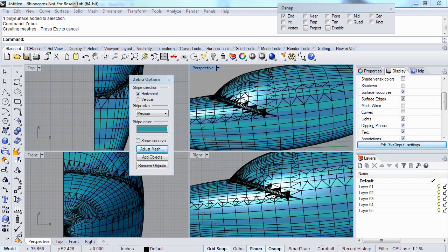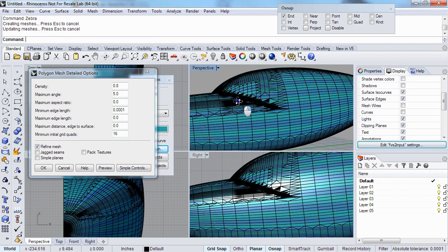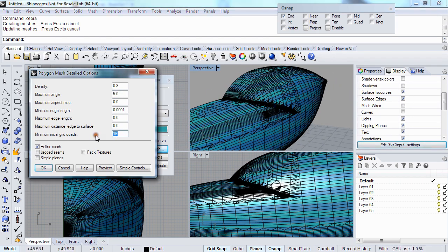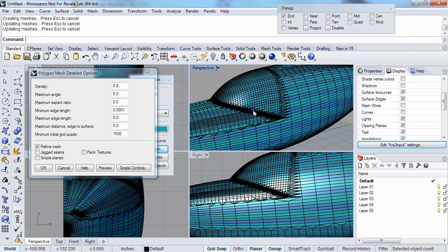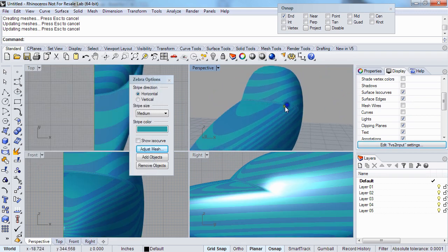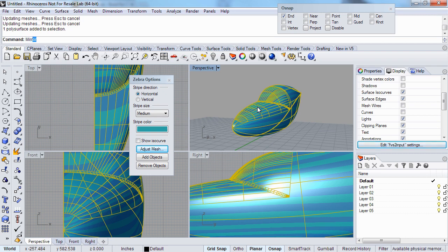it looks pretty smooth. I can crank up the mesh settings to make that a little more detailed. Of course, whenever you're dealing with analysis meshes, you want to set them really high, higher than you normally would. The results there are not bad, not too bad.